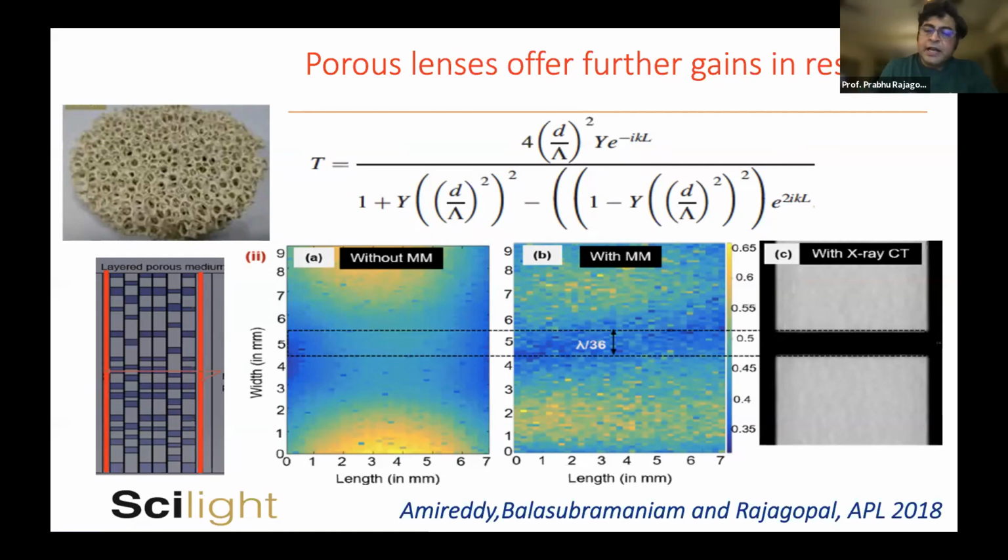So with ultrasonics and in general with diagnostic tools, there are two approaches to look at it. One is a macroscopic overall approach where you say property and its degradation. And the second thing is a microscopic approach where you're looking at cracks, we're looking at delamination and so on. So indeed, a lot of insight is possible.